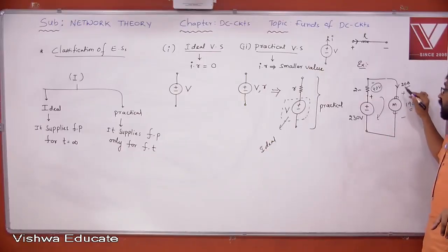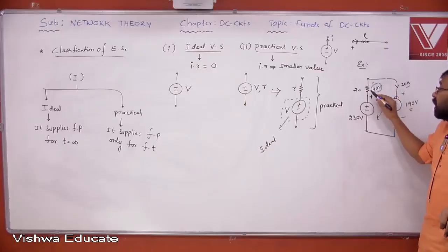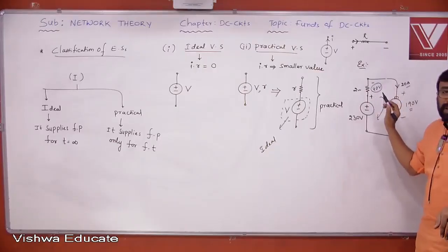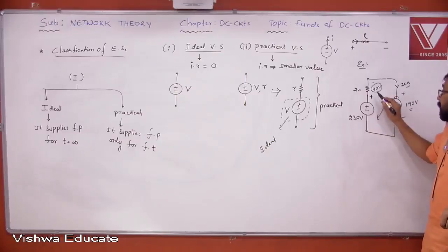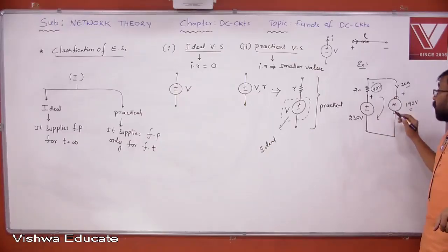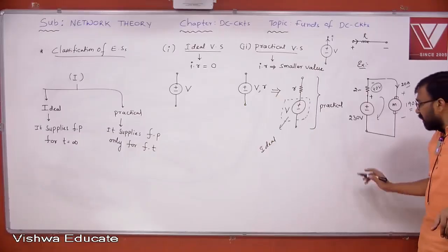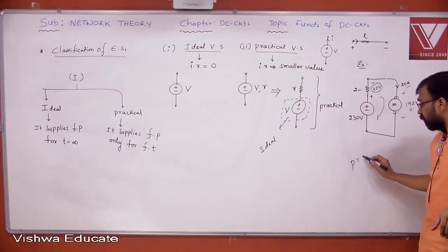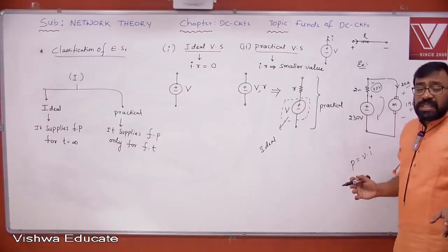And because of the high load current, what's happening? The transmission line resistance into that load current will give you the drop across that resistance. How much? Let us say, in this case, 40 volt. 230 minus 40 will give you 190. That means the motor is experiencing the low voltage problem. What will happen when the motor is experiencing the low voltage problem?